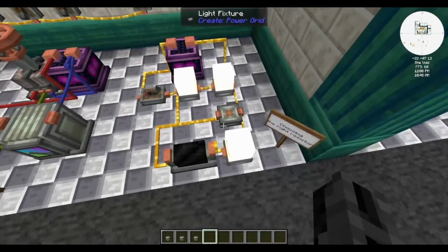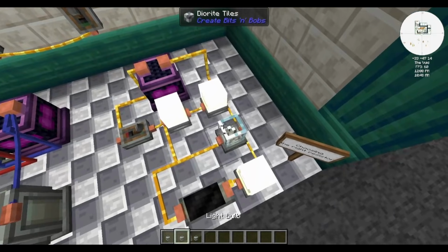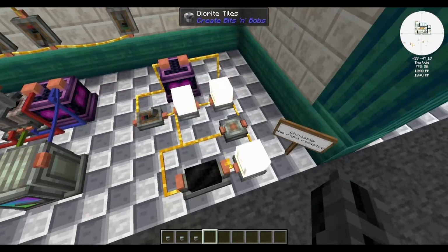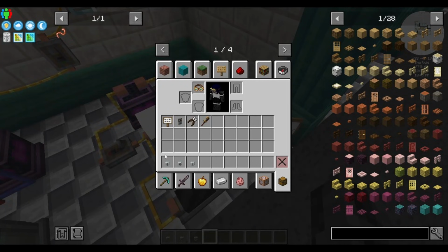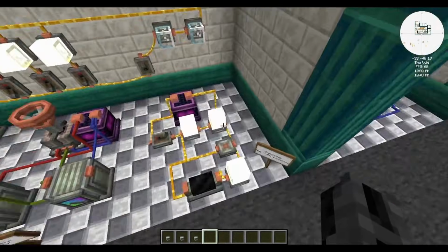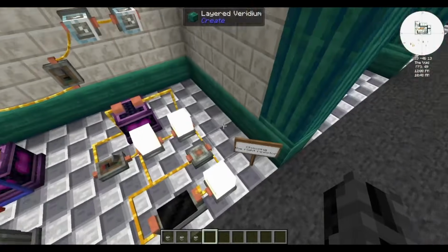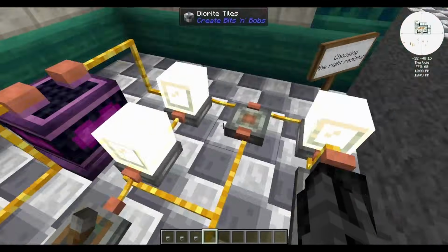Meaning, at lower voltages where it's not lighting up, the resistance might be higher than the one that's calculated from the power. That's why it's called equivalent and not the actual one, because the actual one depends on the heat of the filament.